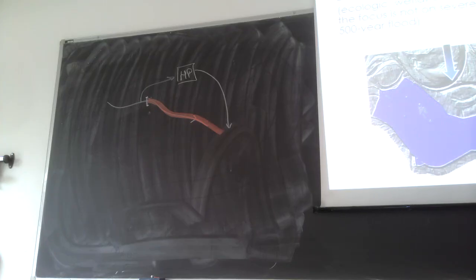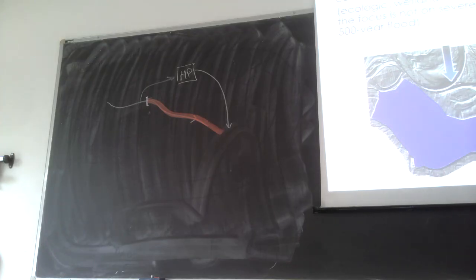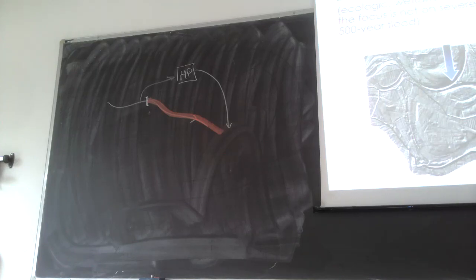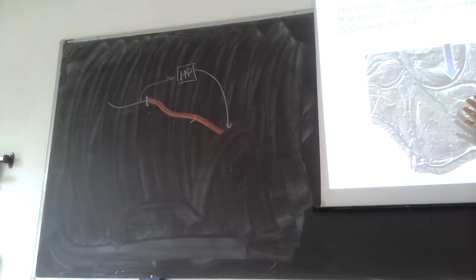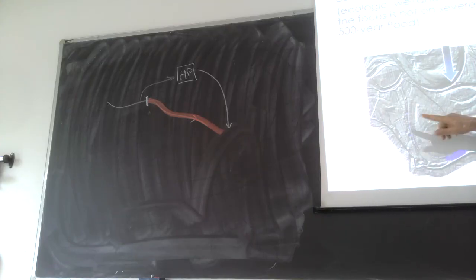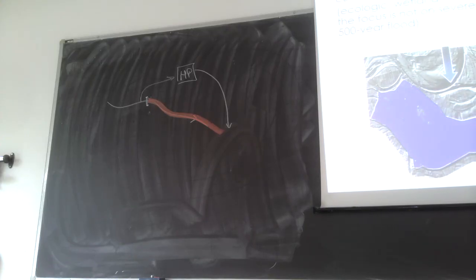Combining the information on the river stage with a digital elevation model, you get the amount of land that is inundated, wet, has the presence of water in time. You can represent, let's say, the duration of the flooding in time, which might be very informative for agriculture.